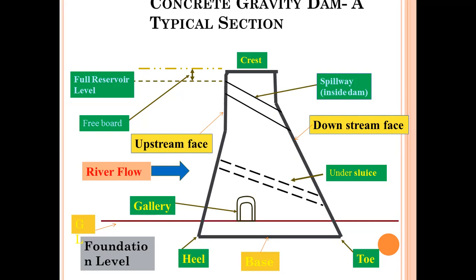That's why in designing or in the calculation of stability of dams, we must calculate the stability in two conditions, that is full reservoir condition and empty reservoir condition. Next, where do we calculate the forces? In both cases, in full reservoir condition and empty conditions, we must calculate the forces at heel and toe. The forces between heel and toe should be equal.